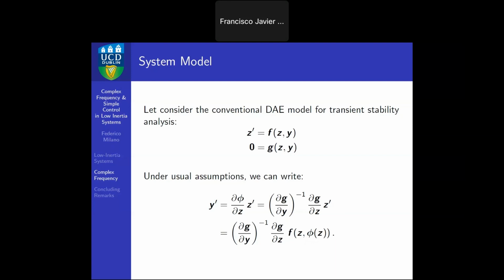So it has internal variables, state variables. y can also be the voltage of the point of connection, or any other variable that is in the device. But in particular, it can be P and Q of the device. Okay, so that is the point. So I can express the derivative of P and Q as algebraic variables as a function, as you see, of the states and the differential equations and these Jacobians. Now, this calculation can be very complicated or simple depending on the controller, but it can always be done, particularly during a simulation or offline, because we have these equations in a model, right? And we can always do that.